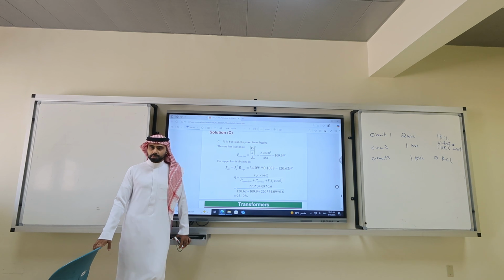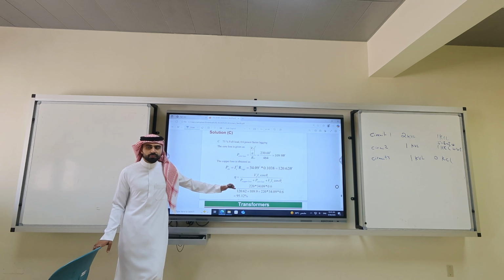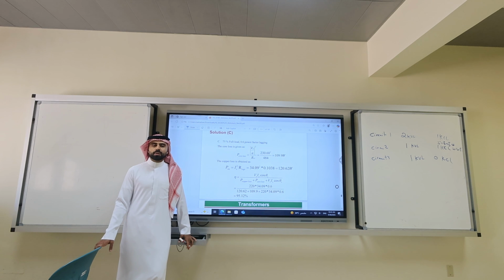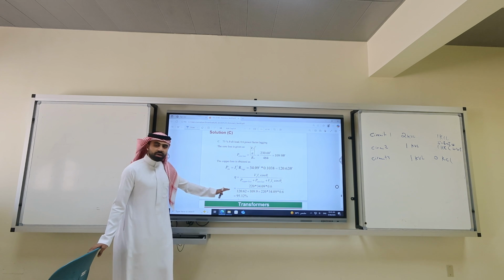So, is it an optimization problem? Yes. Because for transformers in neighborhoods, sometimes the demand might be lower or higher. Well, most probably it has to be more. So that's why in real life, most transformers operate below average maybe. Would you rather operate at 93% efficiency and your customer is happy? Or operate at 99% and your customer cannot connect certain loads? It's your choice. Now we bring a question about economics, but you get the idea.